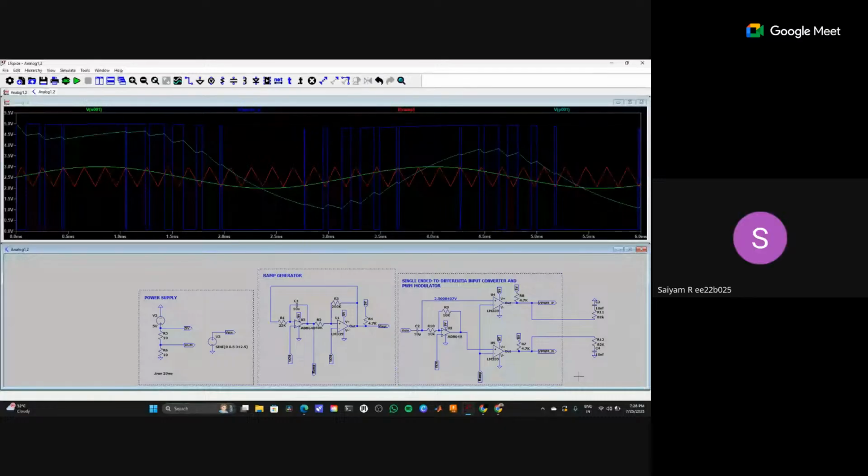Right now if I calculate, I'm getting 1.2 kilohertz. So you can increase that to 10 or 20 kilohertz, because if your bandwidth is too low, then your signal will get attenuated. That's why you are getting a weird kind of sine wave after filtering.